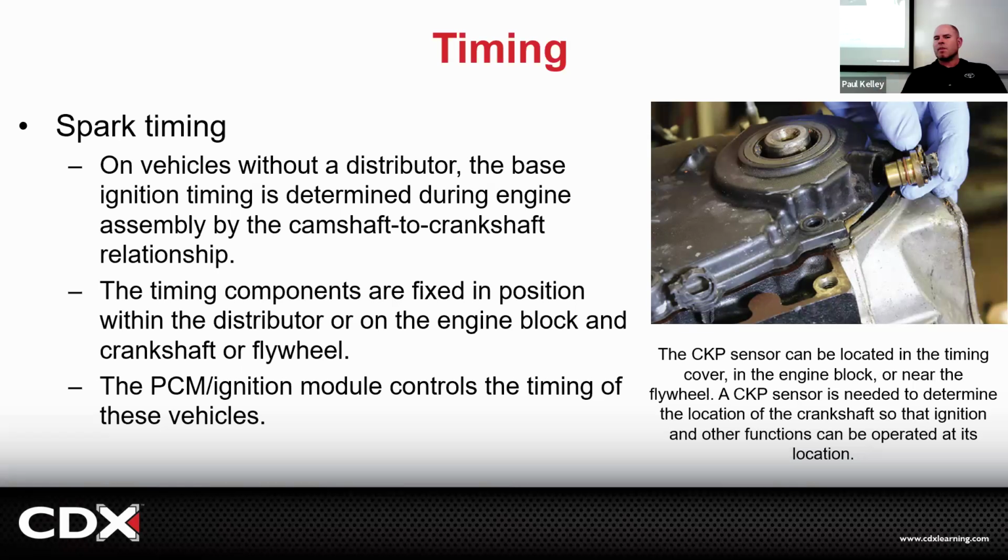So back in the day, the manufacturers were not really trying to advance the timing too much. They were going conservative because the fuel economy standards were pretty low and the emissions requirements were pretty simple to meet. So like, we don't really need to run really high advanced timing. But as they tried to get better emissions and better fuel economy and still more power, now they're running pretty close to the absolute limit of what you can run for advanced ignition timing.